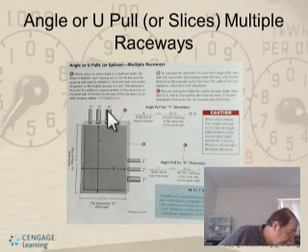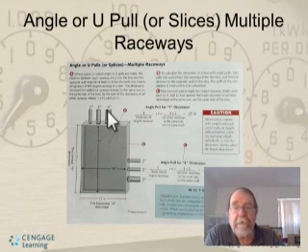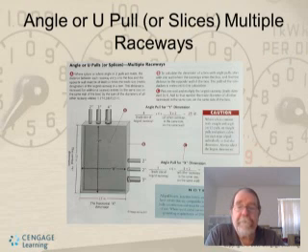Okay. All pull boxes, junction boxes, and conduit bodies must have covers that are compatible with the box or conduit body construction and must be suitable for the conditions of use. In other words, if it's outside, it has to be a sealed box. If the box is an outdoor box instead of a box that's going to be inside, it's a little bit heavier gauge metal. The caps are a little different for popping out the holes in the box. So that would be how you tell on that box.